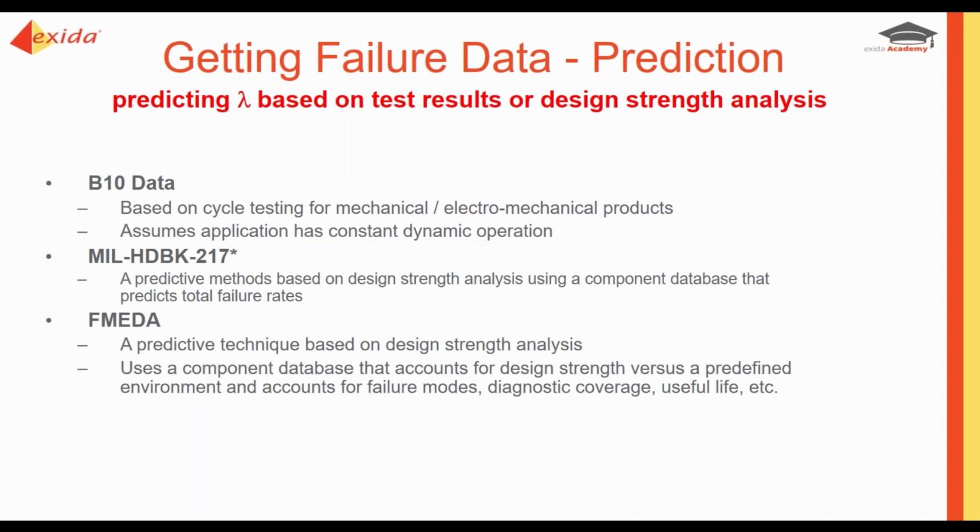B10 data is also known as cycle testing that you may have heard of, and that is based on your test results of a repetitive motion. This test, first of all, assumes that the application has constant dynamic operation. What does that mean? That means you're in a continuous or a high demand mode of operation. So is your SIF a robotic or machinery application? If so, B10 and cycle testing may be a valid method for you to predict your failure rates.